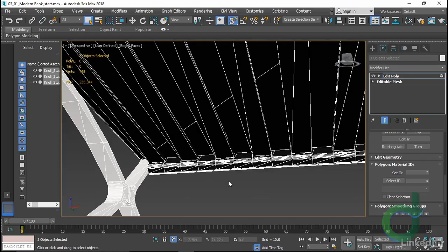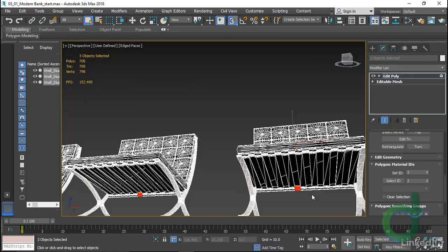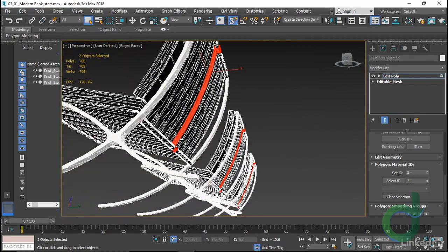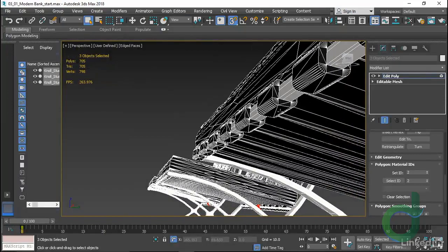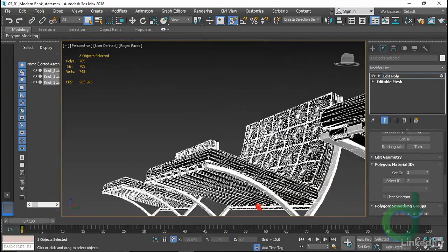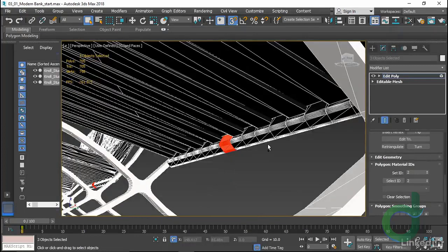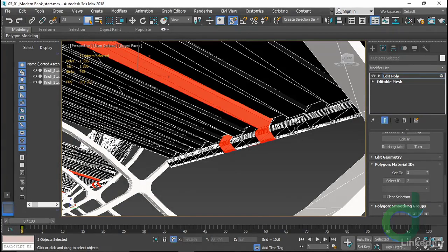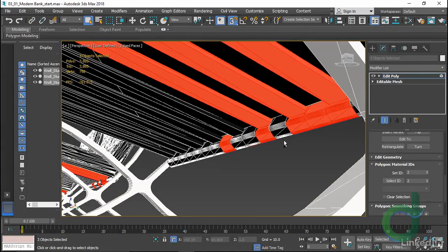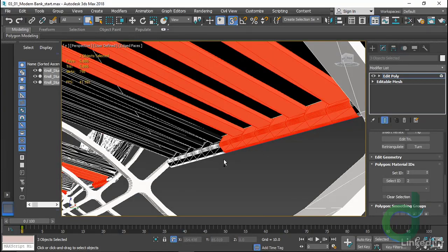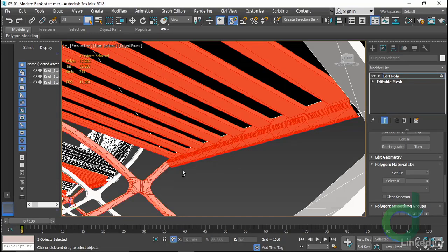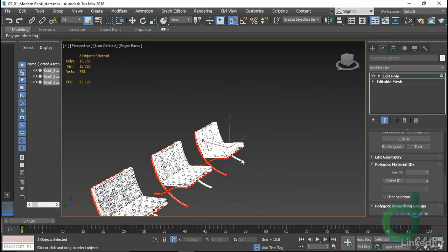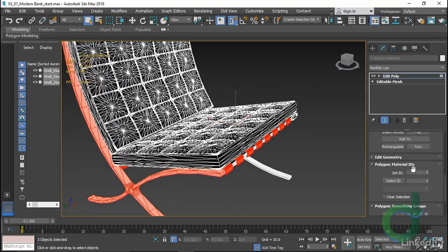Here's how I'll catch tough stuff like this. I'll zoom into a place I can see it and use my crossing selection to start to grab these different pieces. This is a unique one because we've got a lot of pieces that are, well, intermingled. I'll use that crossing selection, going across those pieces and selecting them. It'll take a little work, but remember these are instanced objects, and so working by polygon should work fairly nicely. I'll make sure I don't have any of the sides selected and change the IDs on these to 1.